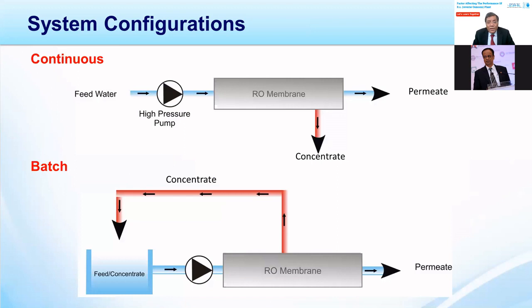We have a couple of options to work with. I have observed that in industry, sometimes they require ultra pure water as a minimum requirement, not a continuous requirement. You can have a continuous process, or a batch process, meaning you can collect your RO product or permeate in one tank and recirculate it through the same RO to get better quality.